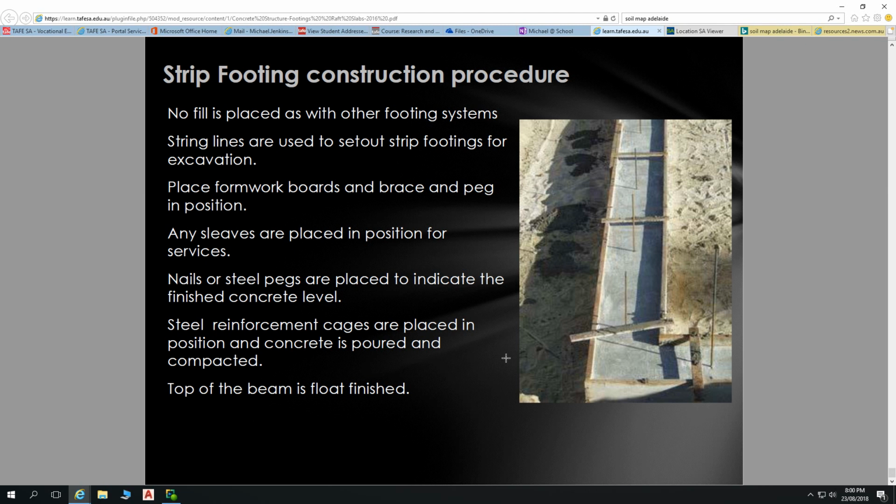And in this scenario here, they've got a concrete strip footing, and then they've fixed their reinforcing bars into that. My guess is that's to go into core-filled concrete block construction. So you put your concrete blocks on top of that with your mortar in between your concrete blocks, and those steel bars, they're spaced at 400mm intervals, and they will slot in with your holes in your concrete blocks, and then you pour concrete into those concrete blocks, and then you put other reinforcing that will lap over top of that, and then lay more blocks and fill those with concrete.